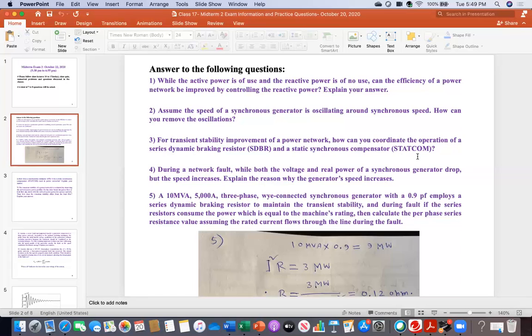The parallel connected device is dependent on voltage. Unless there is the required voltage, the thyristor or IGBT diode cannot operate. During the fault, voltage has gone almost to zero. Therefore, with that very low voltage, the parallel connected device cannot operate.